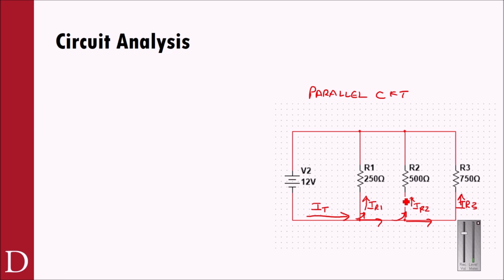somebody taking that exit. What's unique about that, though, is Kirchhoff's law says that if I take a complete path in a circuit, I have to consume that voltage. So it makes it a little easier, because now what I know is VR1 in a purely parallel circuit has to equal 12 volts. Why? Well, if I'm an electron flowing this way and I flow up through R1, if that's the only